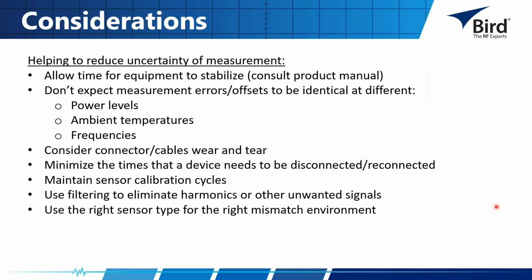So again, when you plug your sensor in and you've got some dummy load attached, there's going to be heating up, especially if you're going at a higher power level. There's going to be heating of cables, connectors, the load itself, the sensor. There's going to be a lot of movement over that initial period of time when you first turn everything on. So it's always good to consider trying to find some stability period and just wait until you get to something that's a little more stable.